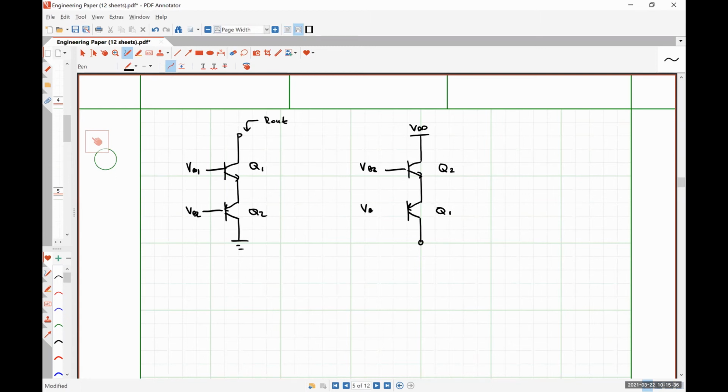2, VB1. So in all the previous examples, my cascoding was carried out by connecting an NPN transistor to an NPN transistor or a BJT transistor to a BJT transistor. But now I have effectively a complementary circuit that contains both an NPN transistor and a PNP transistor. Is this an effective method of cascoding or boosting the output impedance? Anybody have any thoughts?